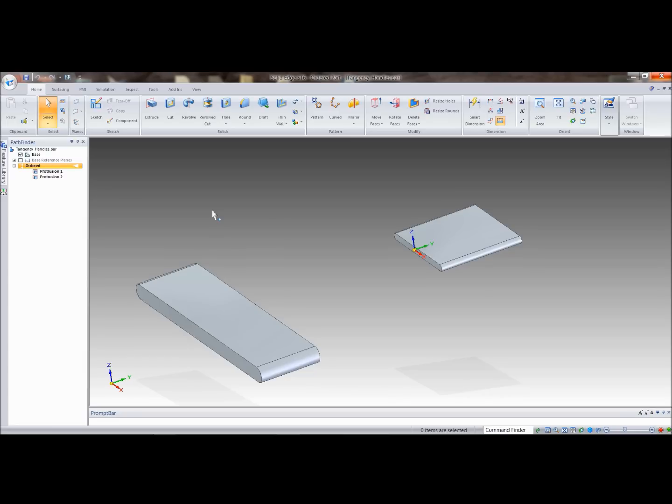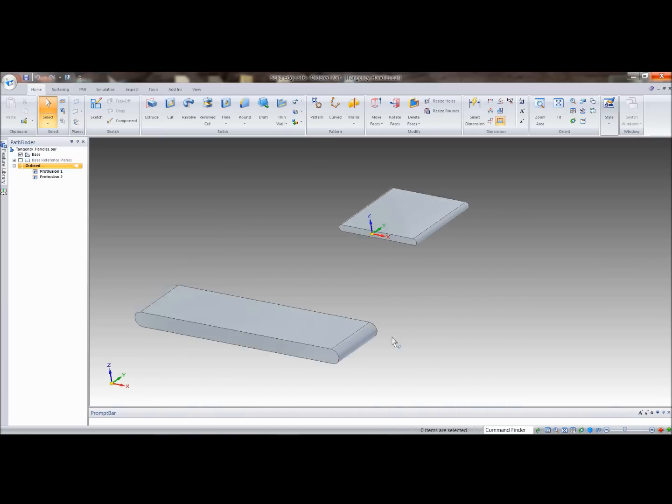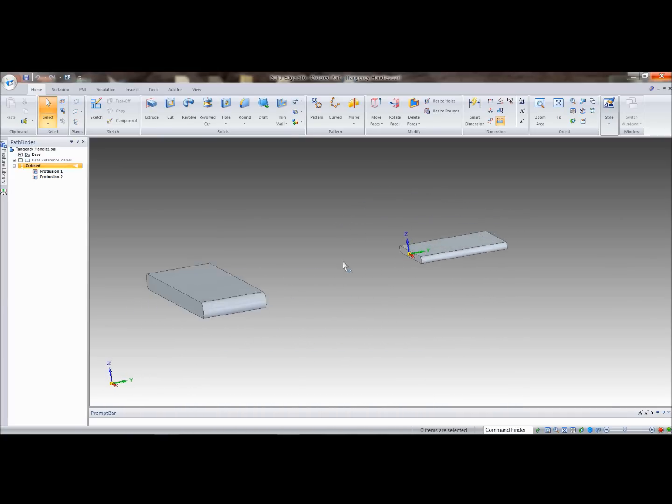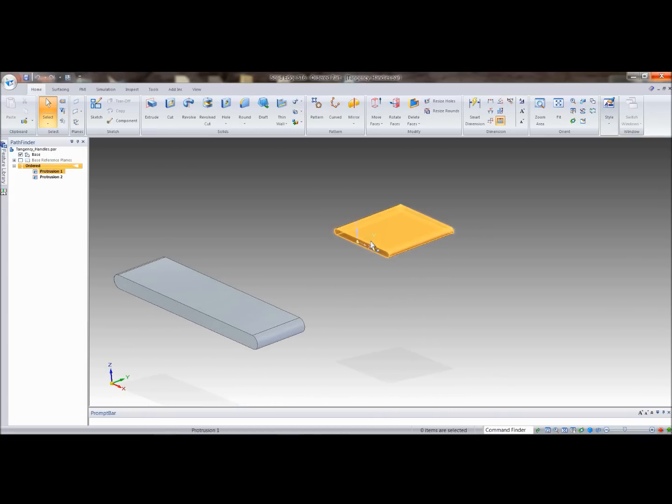Another enhancement added in ST6 is tangency control handles. They've really enhanced the way you can control how the part comes together in lofts and sweeps and those types of things. When you're creating blue surfaces and those types of things, you really have a lot more control of how these surfaces come together. To give you a little example of that, I've put together this little part that's got a couple of pieces already in it, and I want to loft a section between this part of the part and this part of the part, and I'm going to show you the different ways that you can utilize the tangency handles so that you can get what you're looking for.